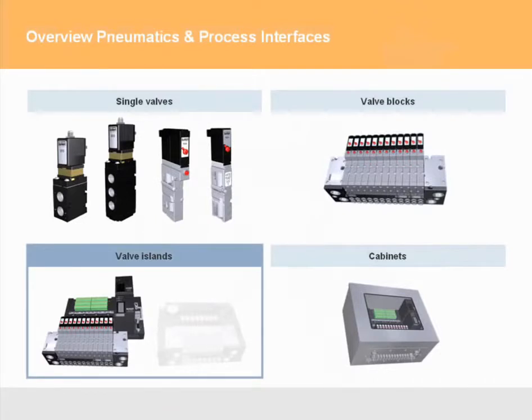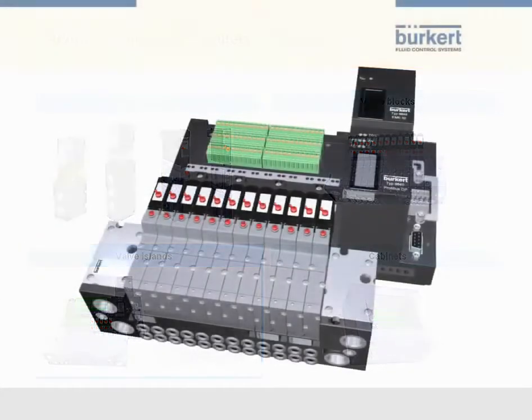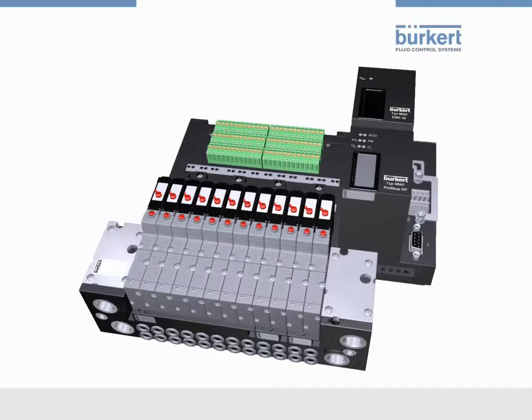Valve islands and automation systems are constructed in the same way as valve blocks. In contrast to these, they offer a common electrical actuation of the valves. Common connection, multi-pin or field bus interfaces, for example Profibus or Ethernet, may serve as the communication module. But what is a field bus? Tom will lead us through a short excursion into field bus techniques.